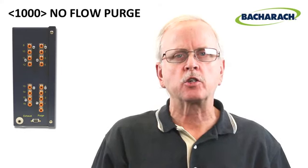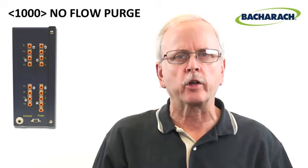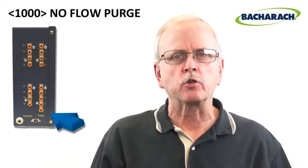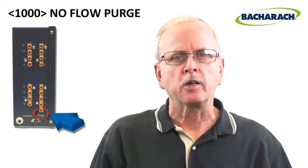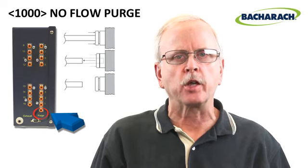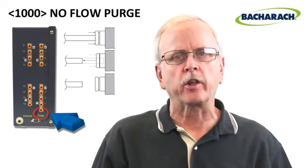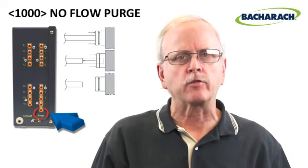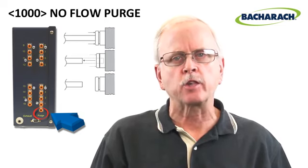So if your MZ shows a no-flow purge fault, you may have a clogged purge line or a clogged end-of-line filter on your purge line. To diagnose these issues, locate the connector on the purge line on the side of the MZ chassis. Disconnect the purge tubing by pushing in on the connector while simultaneously pulling out on the tubing, effectively eliminating that whole zone. Next, wait for the MZ to cycle through all active zones and purge. Then verify that the no-flow purge fault has been cleared.